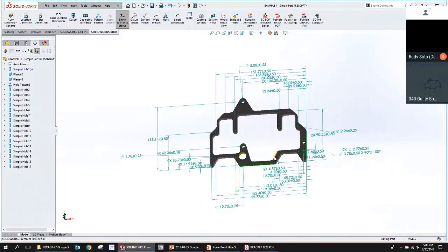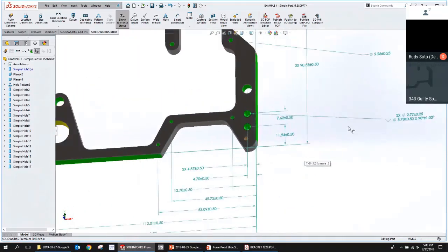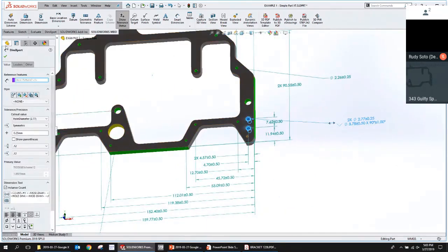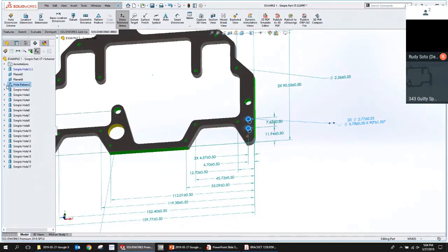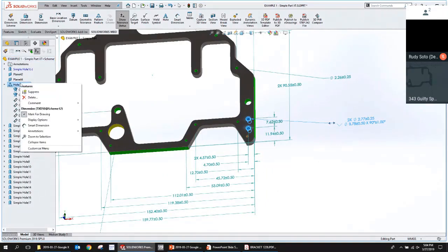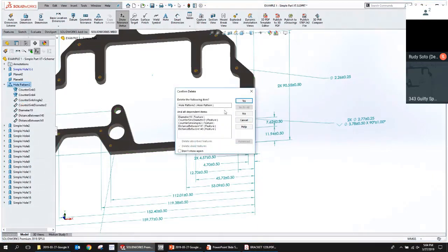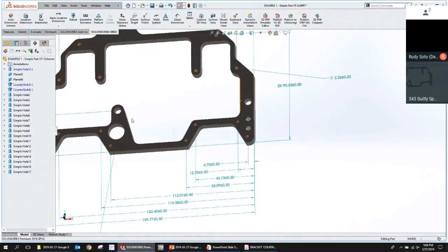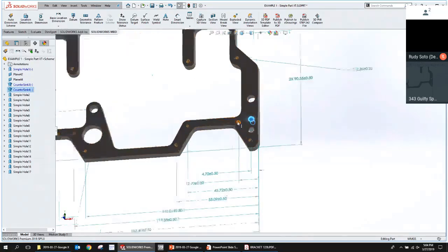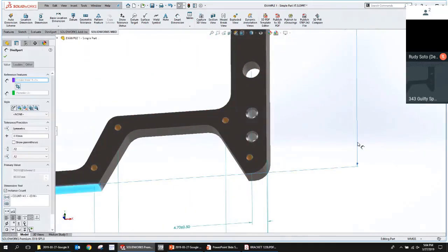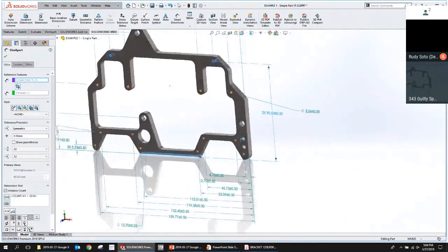Okay, and SolidWorks goes through and applies dimensions to all of those features. Let's see here. So we get this whole pattern here, right mouse button, and I thought there was an uncombine. When you multi-select these, there's a combine option. I wonder if I delete this, if it'll just... Yeah, I pulled them out, but it got rid of the dimensioning as well. So I would have to go back in and dimension those.